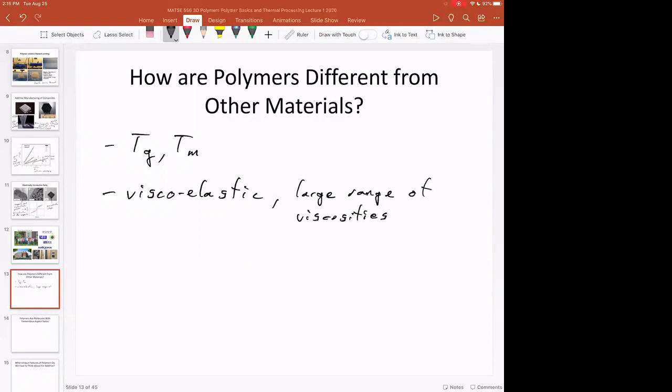So just like in the previous diagram I showed you, that viscosity is really going to matter for extrusion out of that 300 micron orifice. And so it turns out that the viscosity of a molten polymer is about 3 orders of magnitude higher than the viscosity of molten iron. And so that's really going to influence the processing or the shaping of the polymer for sure. What else?